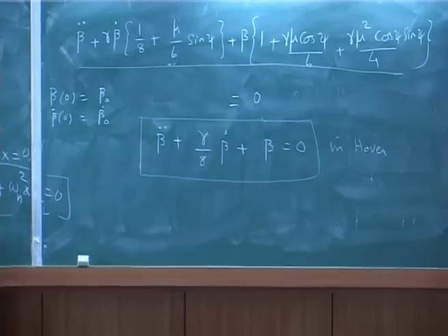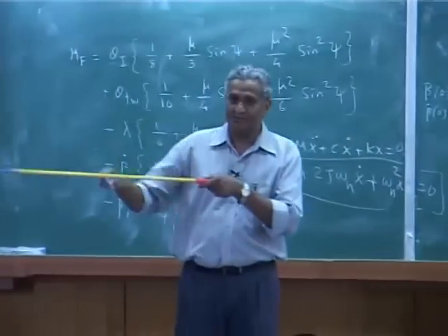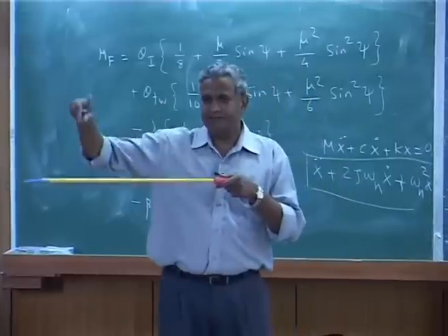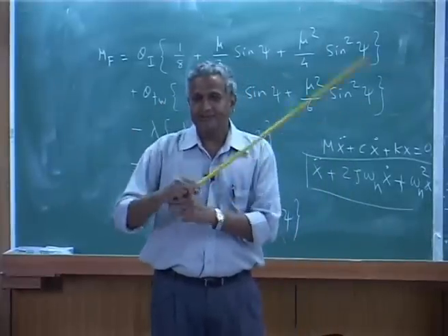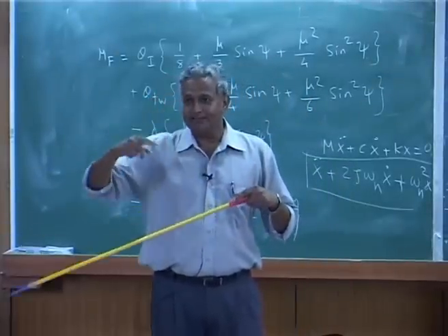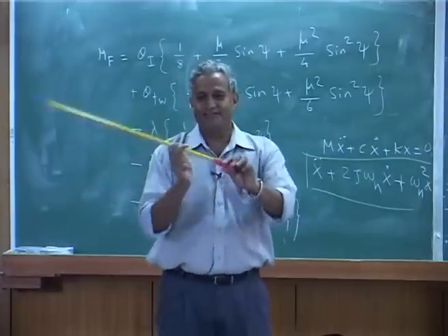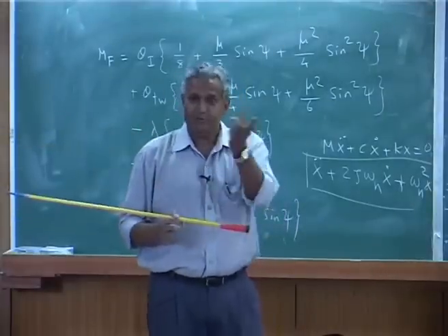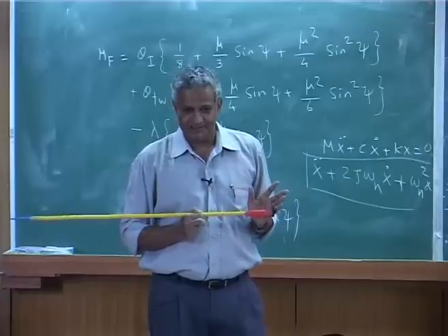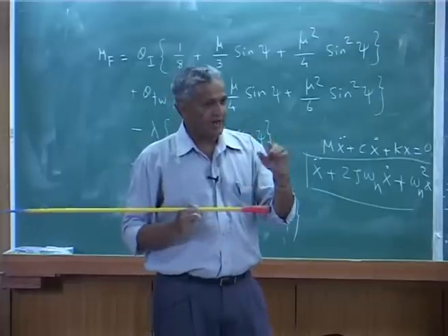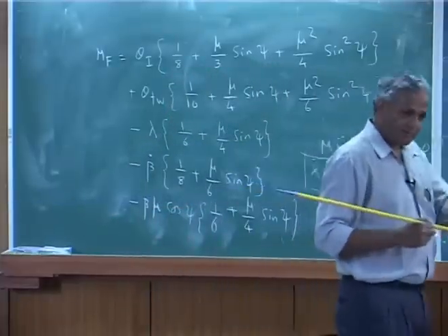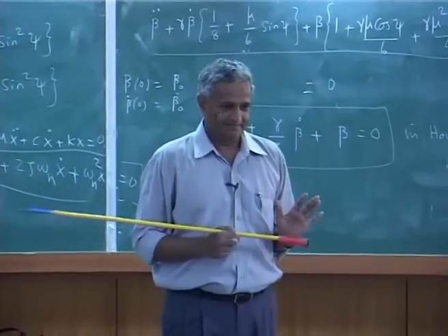Okay. So when the blade, if it is rotating, if you tap it, it will oscillate. The time for it to go up and down, one oscillation, is exactly equal to the revolution time. Okay. So the rotor RPM is actually the flap frequency.